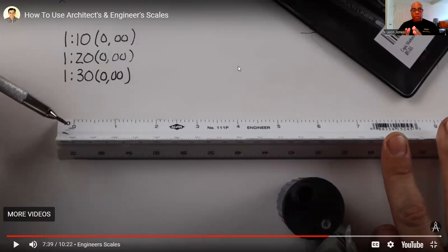But nonetheless, an inch is going to be dictated by the scale. 1 inch equals 30 feet. On the architect scale, everything is conclusive to 1 foot. 1/4 inch equals 1 foot. That's something that will help you with scaling. And it takes skill to scale. You want to get as accurate as you can with all of these scales.